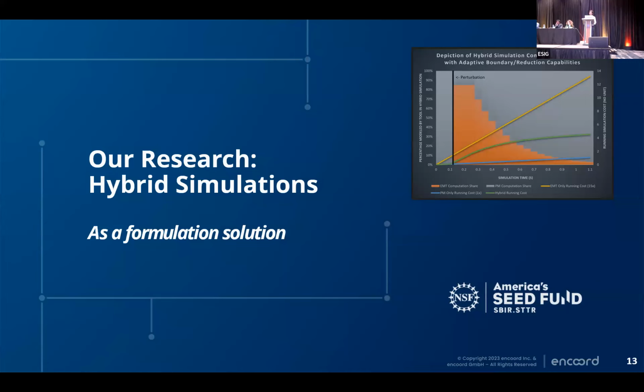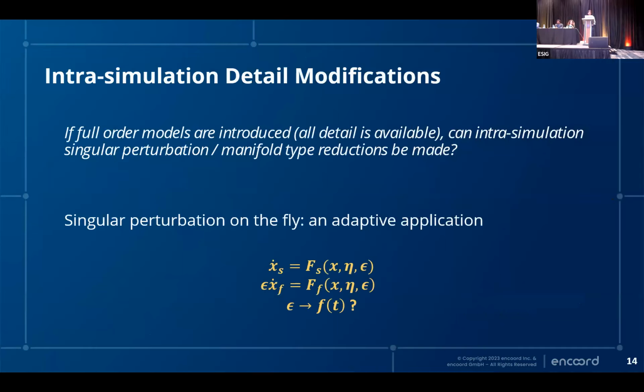The yellow trace would be sort of an interesting representation of the computational cost of an EMT type simulation. You can see it's going to the right and up, so it's getting larger. The blue one could be representative of a QSP. Of course, QSP is missing detail, EMT is taking too long. But if I was able to vary how much was modeled in an EMT type simulator versus a QSP type simulator, then I would have sort of that green trace in there. That is, of course, a huge simplification, but I think it gets the idea across.